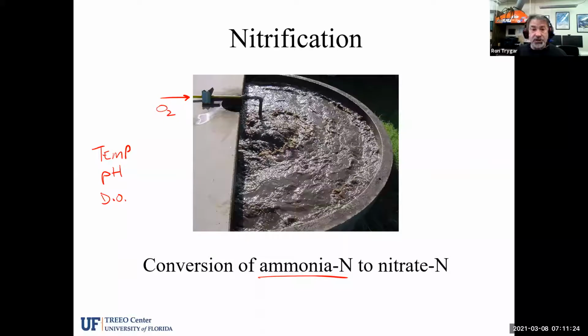But there are conversion tables that use the temperature and the pH to give us a measurement of how much ammonium is really present, based on the ammonia value that we ran with our laboratory equipment, and then converting it into the ammonium proportions based on the temperature and the pH at the time of sampling.